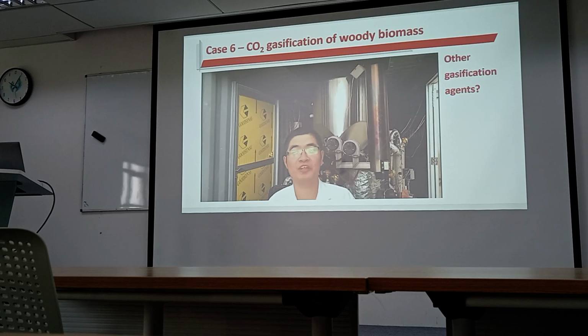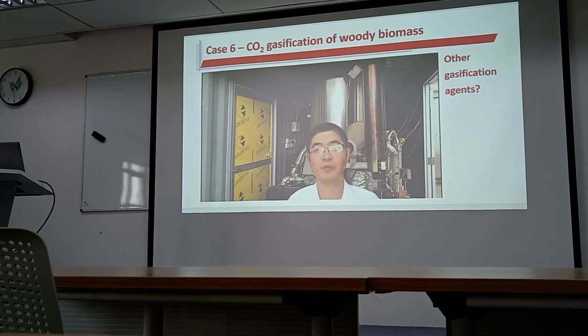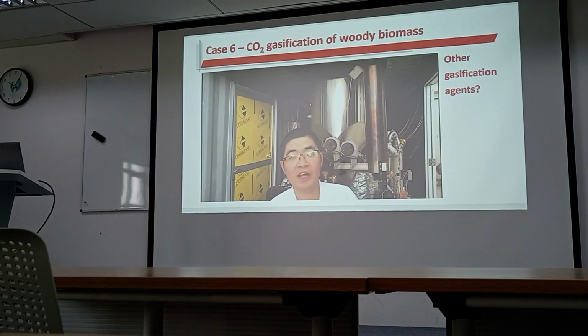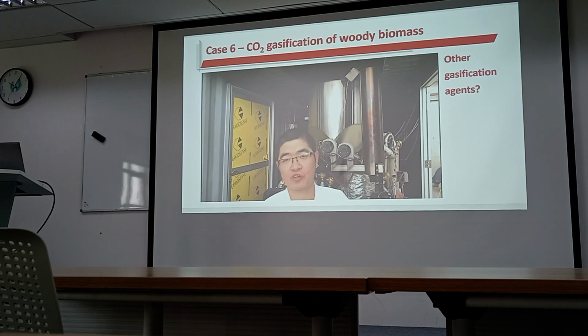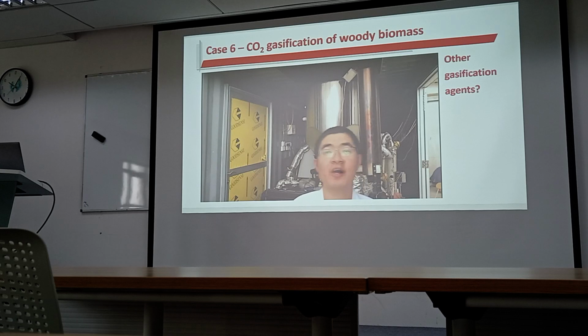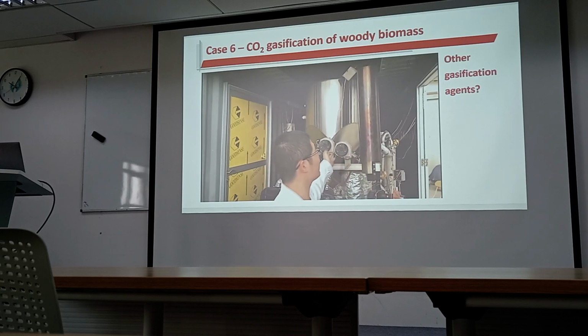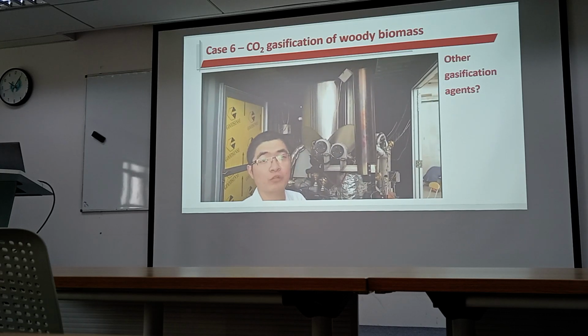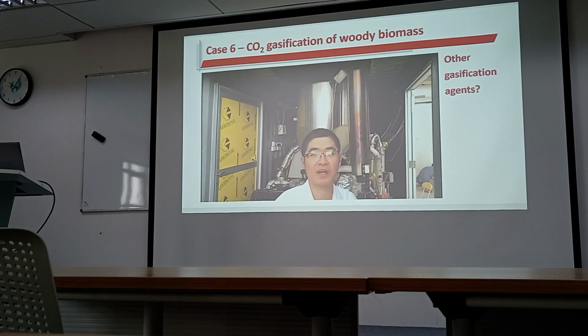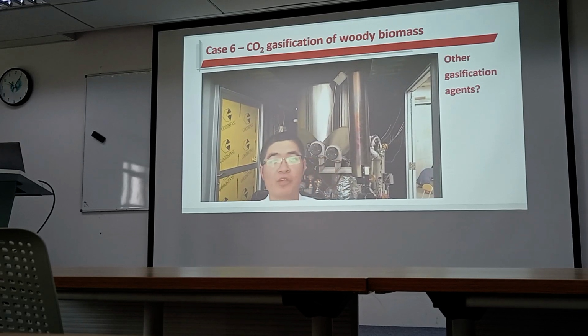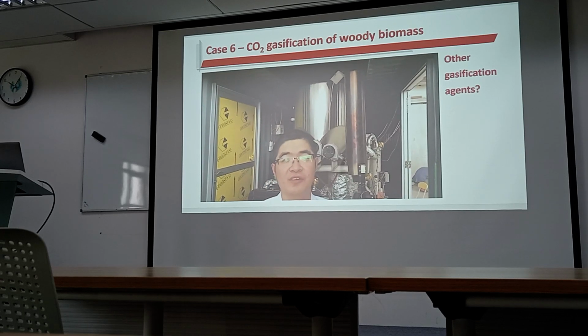Hello everyone, I'm Shen Ye from the E2S2 CSA Group. I'm with Prof. Shiba. And today what I'm going to introduce to you is our CO2 gasification experiment setup. Based on our knowledge of air gasification for the downdraft fixed bed gasifier with a capacity of 20 kilowatts, we further modified it to use CO2 as a gasifying agent.